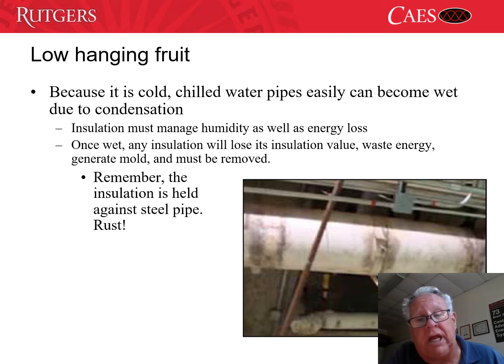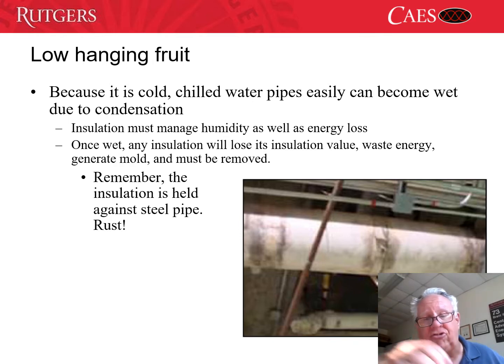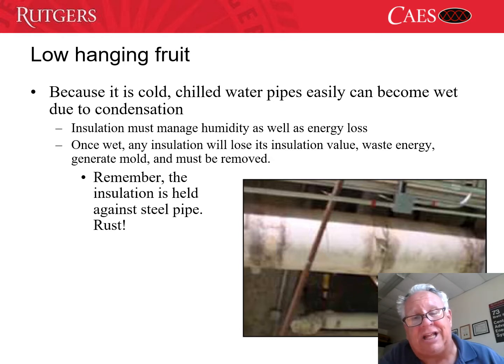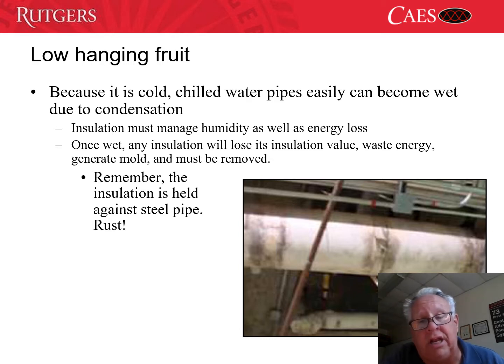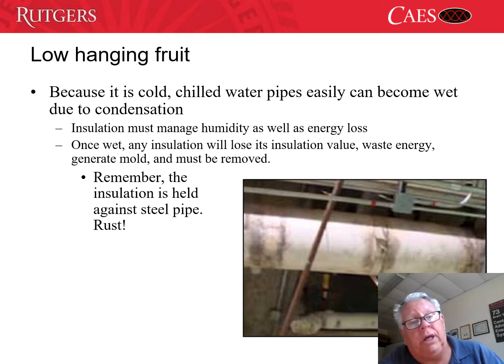Because once you start getting condensation, it makes the insulation wet. And wet insulation is worse than no insulation. If you have wet insulation around a pipe, it actually acts like the pipe is bigger, and you'll lose more energy. Or in the case of chilled water, the water will heat up more because the insulation is wet. You also have the problem of mold that gets formed.